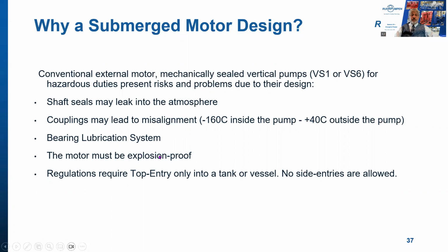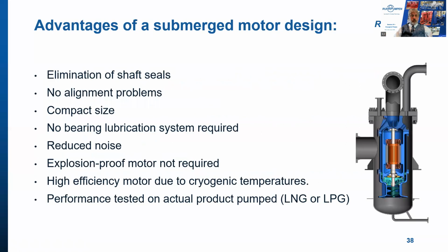Bearing lubrication needs to be considered. And of course, the motor must be explosion proof. Finally, regulations require top entry only into a tank or vessel. No side entries are allowed. So that's why we consider a submerged motor design.